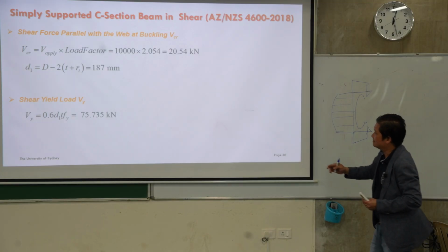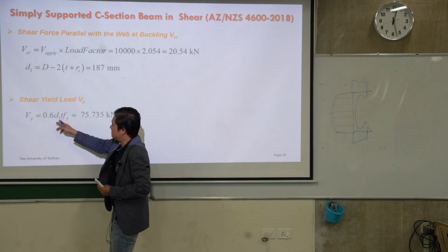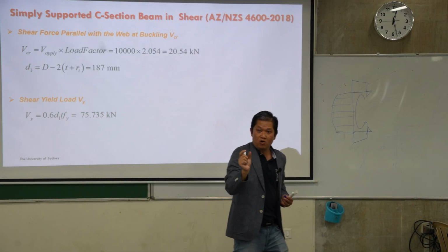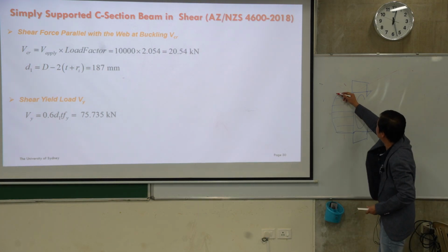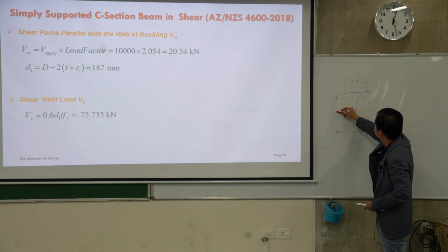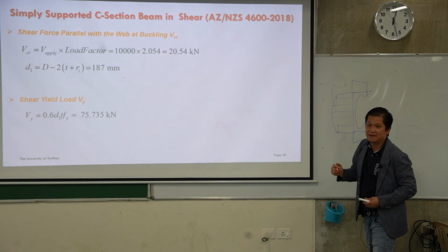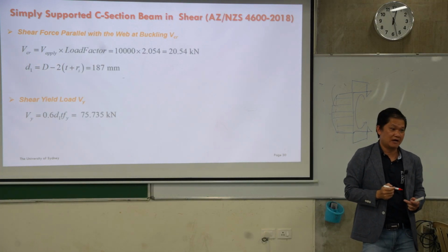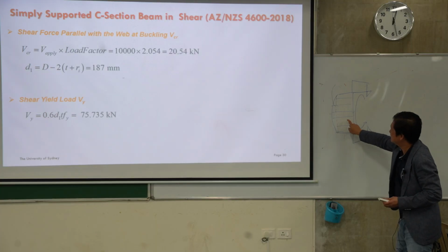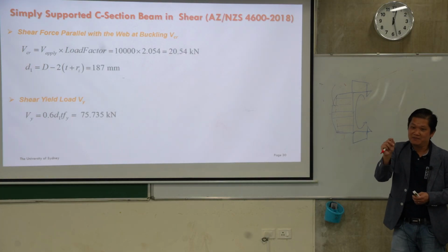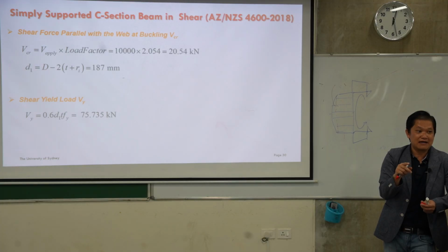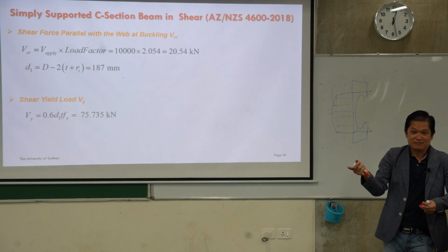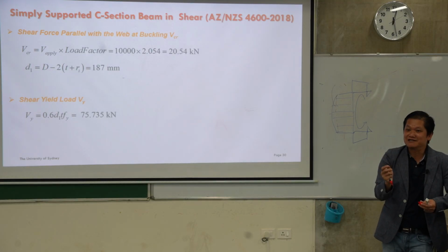But when you calculate this one, you base it on the web only. So normally if you calculate the stress, you have to take into account the average somehow in here. It's not a maximum one. So a little bit tricky. And then you remember in the equation for shear, you calculate with d1 on t, and that didn't take into account the flange.